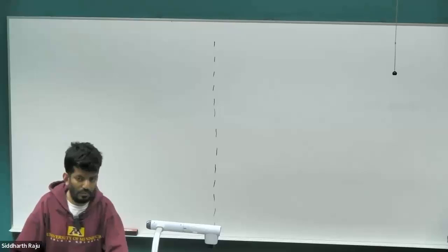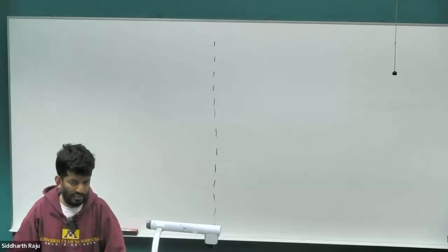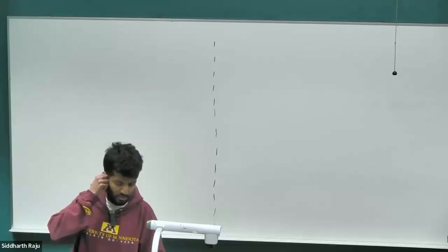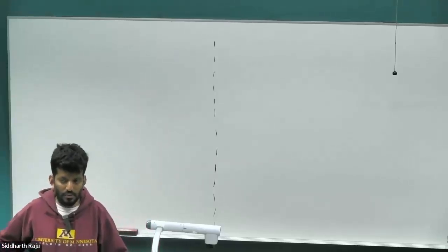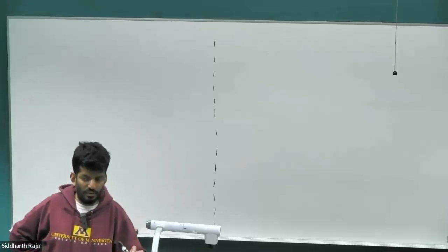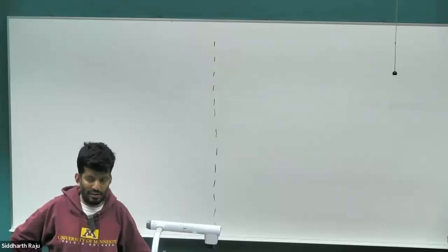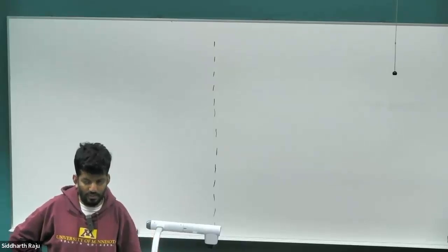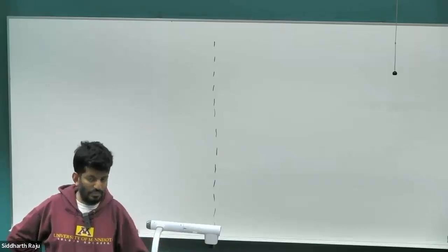And the second topic that I want to talk about is modeling a permanent magnet synchronous motor using numerical simulation software, either MATLAB or Simulink, whatever your choice is. So here, when we go to, again, the advanced vector control course, we would use a different reference frame called the DQ reference frame to model it. As I model the PMAC motor, I'll give you a brief insight as to what the DQ frame of reference modeling would be. But we will be doing it in the ABC domain.